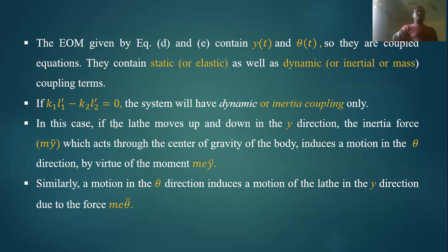Similarly, a motion in the theta direction induces a motion in the y direction due to the force M e theta double dot. So another rotational moment or torque will be produced due to the presence of M e theta double dot, that is the rotational moment.